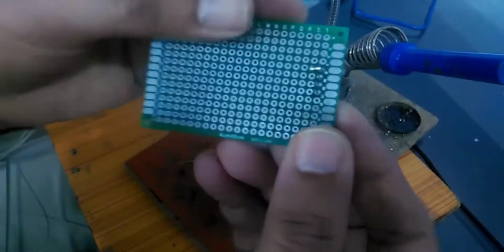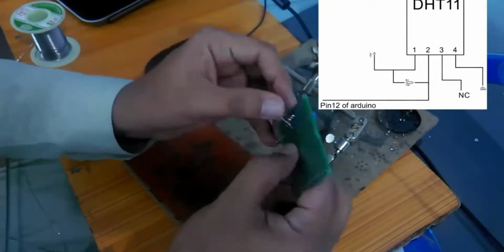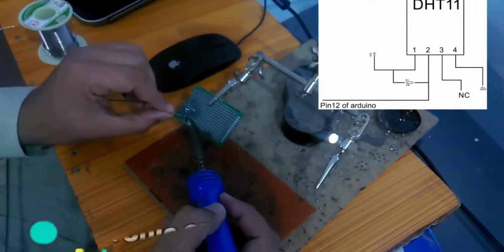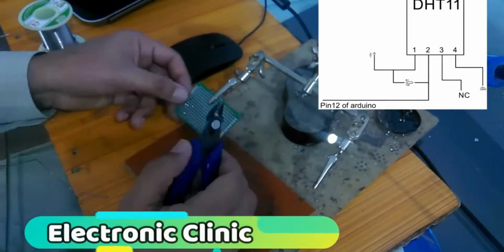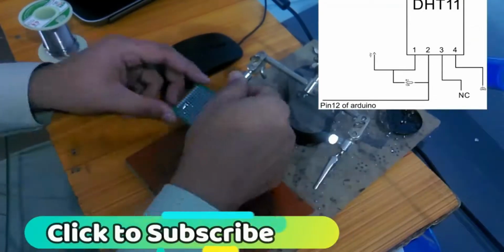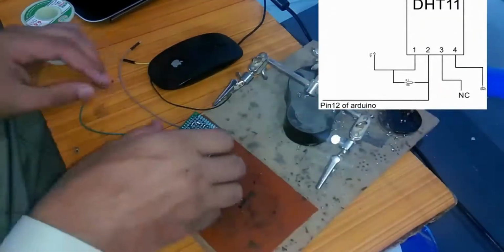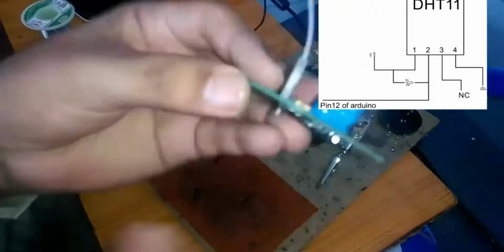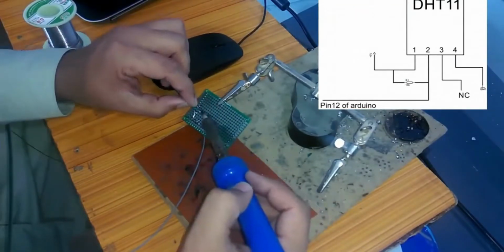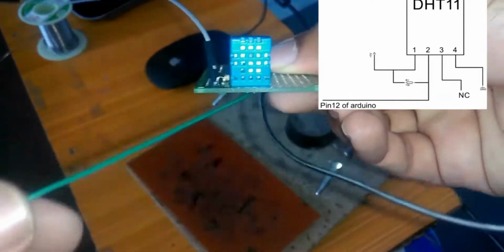So now as you can see there is no short circuit, and we are doing all this soldering as per the circuit diagram which you can see. So now it's time to solder the 10k resistor as per the schematic. So now the 10k resistor is soldered. Now it's time to solder the wires. This is the 5 volt wire which is connected with pin number 1 and one side of the 10k resistor, and now this is the ground wire on pin number 4 and the green wire is on pin number 2. So all the wires are soldered.